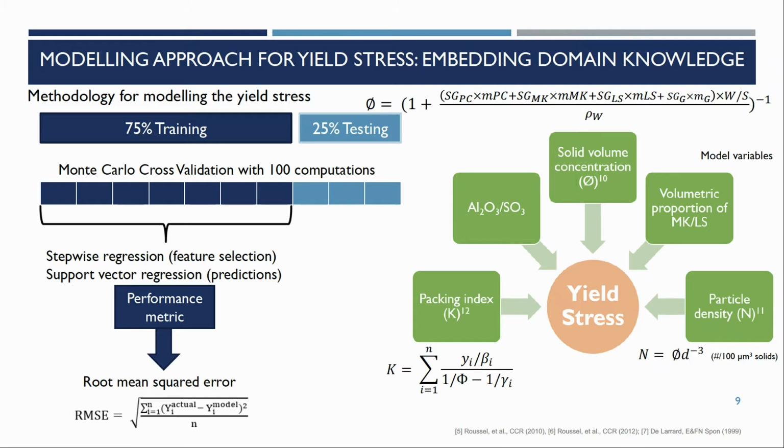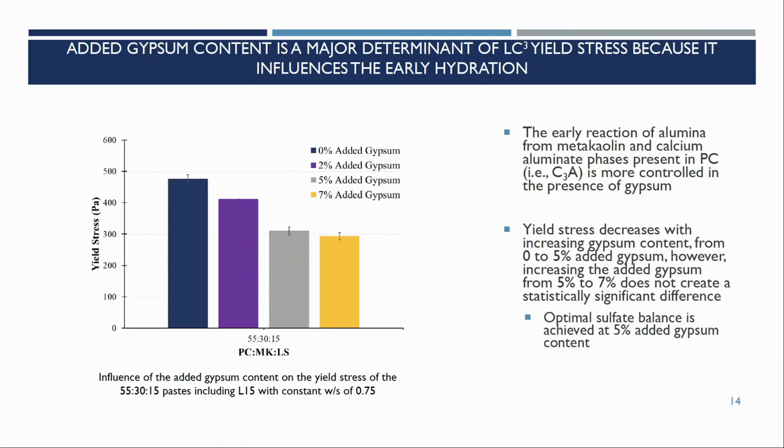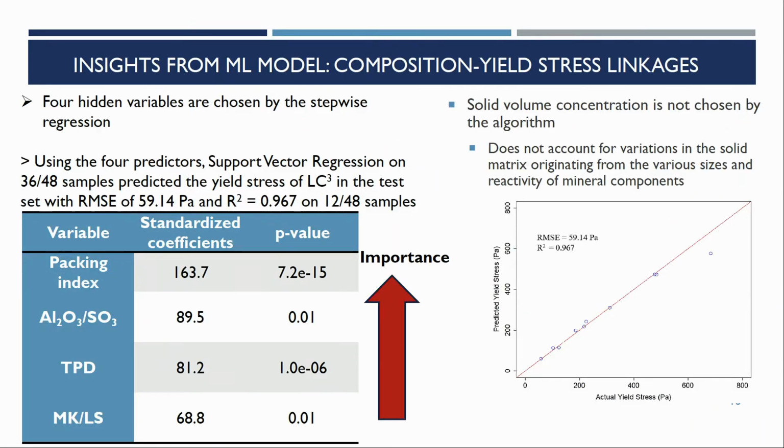In theory, you could make predictions on any new mix. It should be able to accurately predict what that yield stress value is. And then in theory, you can actually invert it, such that if you wanted a certain yield stress, you could ask the algorithm, hey, give me 10 or 100 different mixes. I can constrain all the different compositions and still give you 10 or 100 different compositions that will have that yield stress. So it still acts like a function, but it's more complicated than linear regression.